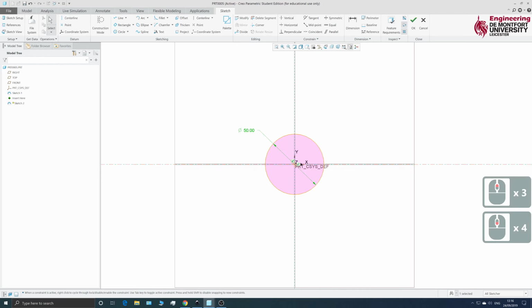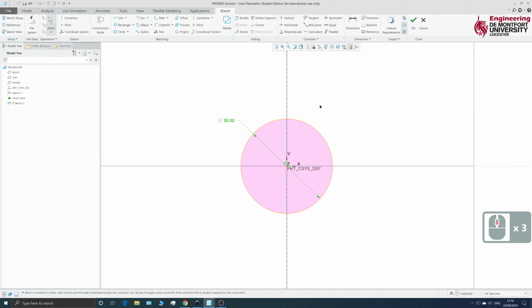Now what we have to do is make sure that the sections of each sketch match. If you draw a square, you have 4 corners, so that means the line will be in 4 sections. With a circle you only have one section, it's a continuous line, so what we need to do is break this circle down into sections.